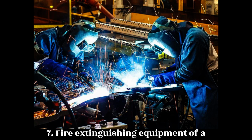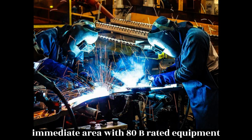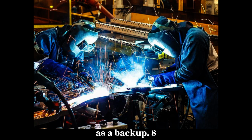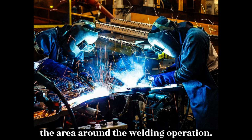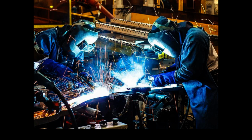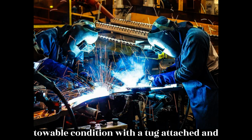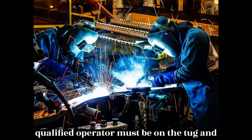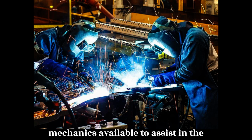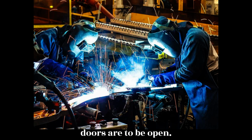7. Fire extinguishing equipment of a minimum rating of 20B must be in the immediate area with 80B rated equipment as a backup. 8. Trained fire watches are to be present in the area around the welding operation. 9. The aircraft being welded must be in a towable condition, with a tug attached, and the aircraft parking brakes released. A qualified operator must be on the tug and mechanics available to assist in the towing operation should it become necessary to tow the aircraft. If the aircraft is in the hangar, doors are to be open.